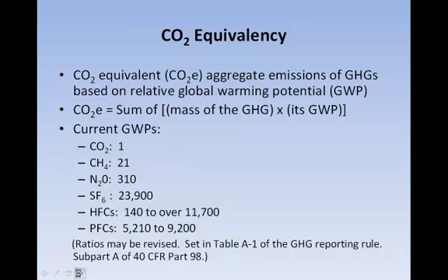The application of PSD to greenhouse gas emission sources is being implemented in steps. The applicability criteria change along the way. And this is all from the Tailoring Rule, again, that was issued back in June 2010. For Step 1, the applicability criteria applies to permits that are issued between the dates of January 2nd, 2011 and June 30th, 2011. Step 2 applies to permits that are issued on or after July 1st, 2011. So this would be Step 1 and Step 2 of the Tailoring Rule.